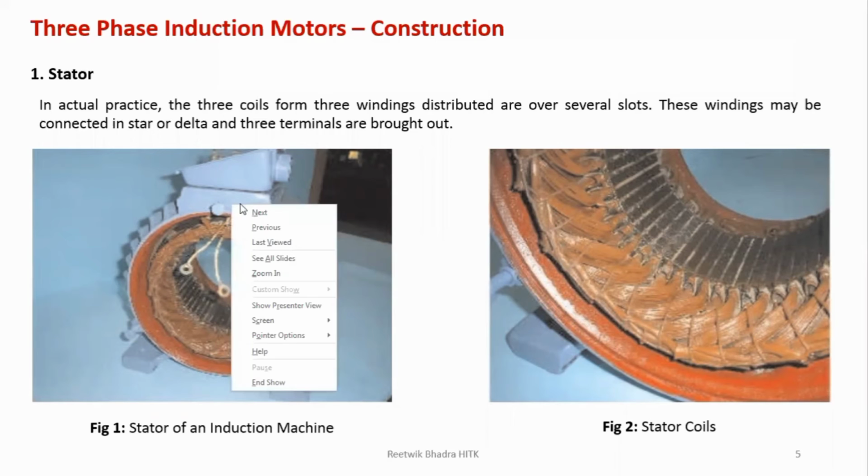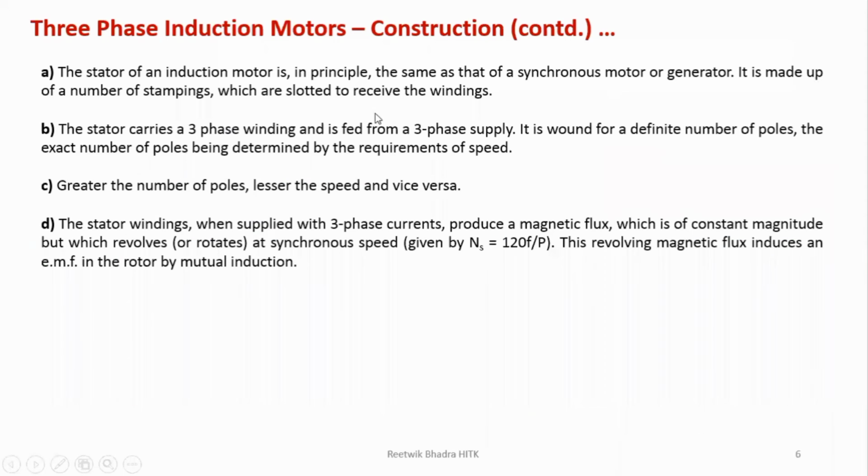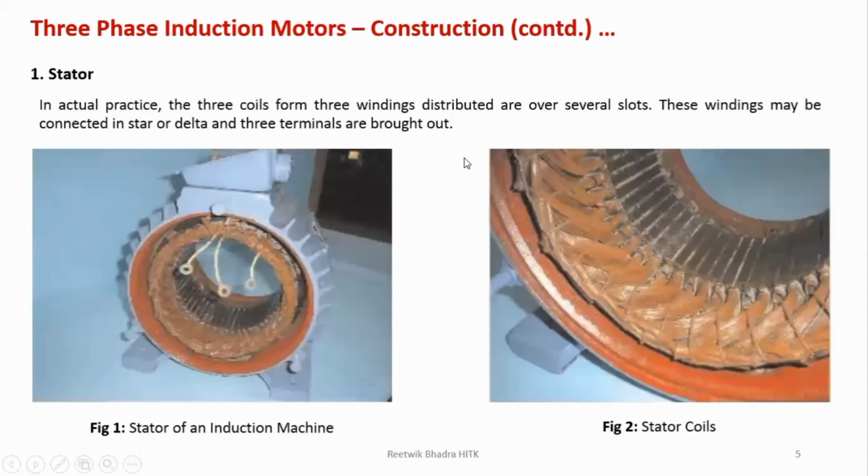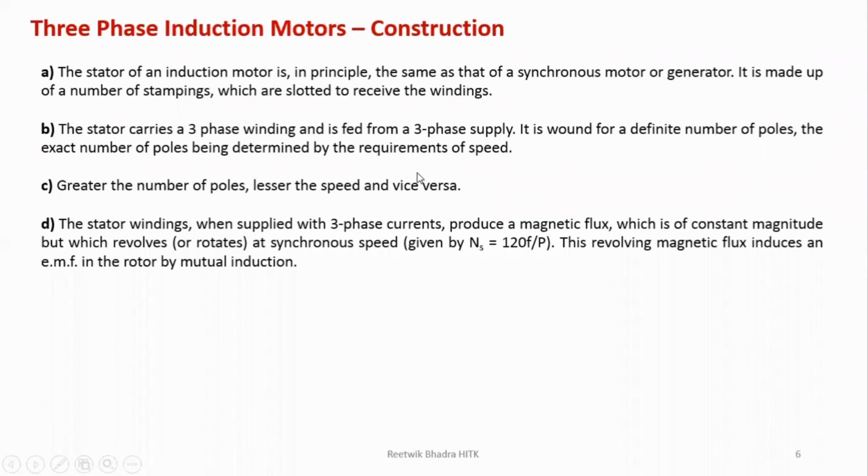Now let's look into some of the important points. The stator of the induction motor is the same as the stator of a synchronous motor or generator. It is made up of stampings which are slotted to receive the windings. So you don't have to go by all these meanings. The only thing you should understand is that there are some slots present over here, and in the slots, windings are placed.